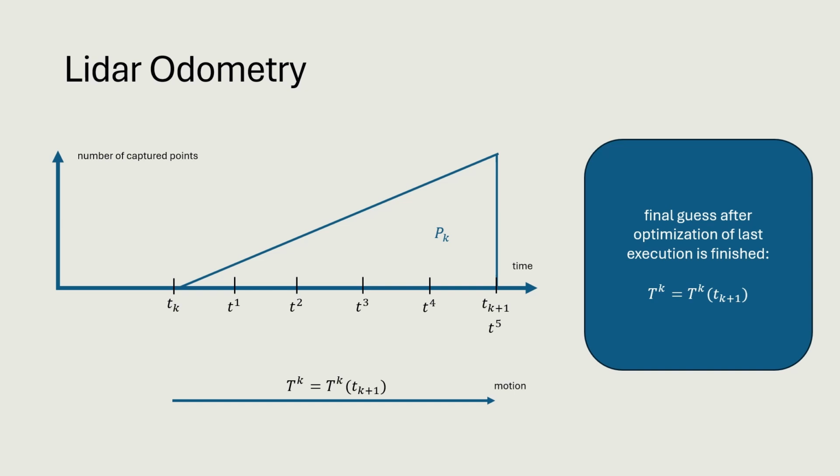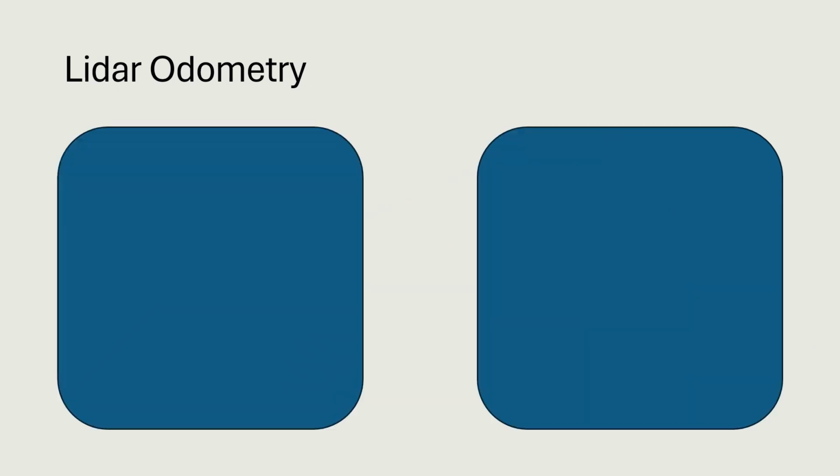The LiDAR odometry module in LOAM and LeGO-LOAM works very similarly. Nevertheless, there are small differences which are important to understand. Firstly, as already mentioned previously, the F sets do not exist in LOAM. The correspondences for the features from F sub e and F sub p to the k are searched by determining the nearest neighbors in the raw point cloud data from sweep k minus 1.